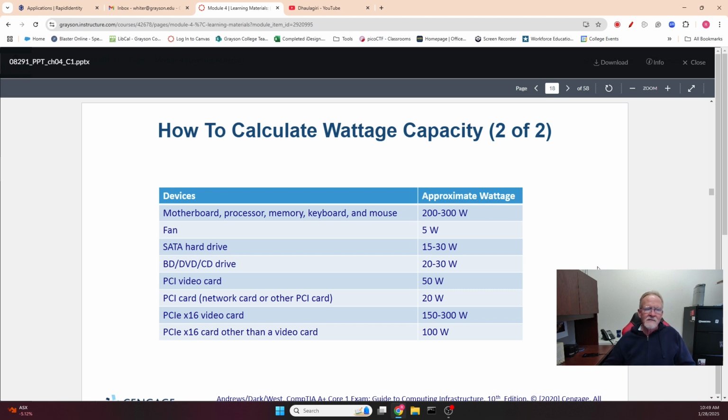Then you need to get 35% of 835, which is going to be about 200 watts, roughly, give or take. And remember, this is give or take. Now, you want to be more precise than I'm being. So you're going to need at least 1,000 watts because you're needing 800 plus 35%. So you're going to at least need a 1,000 watt power supply. You want to add that 35% because you want to give your power supply plenty of overhead, because the requirements for these components are not locked in. So you always want to go bigger than what you need.